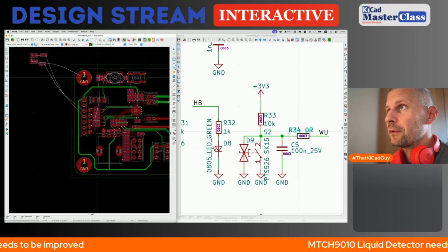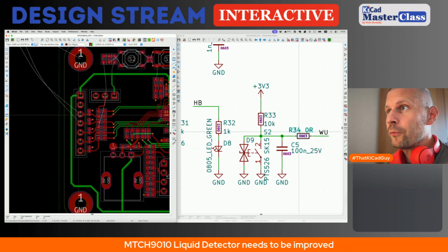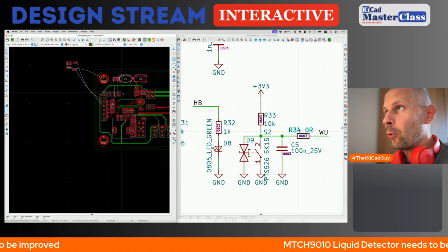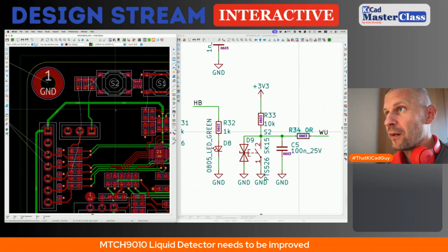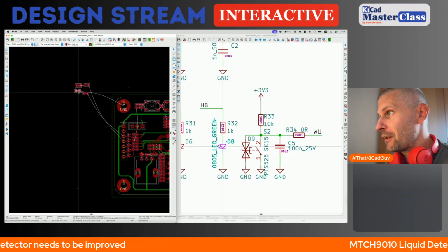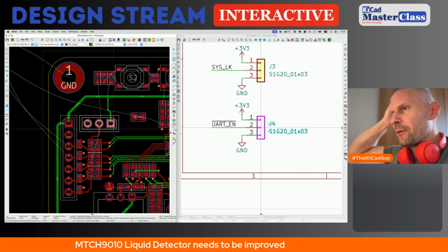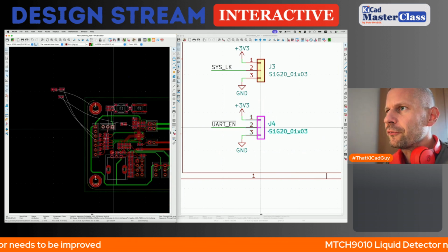I can't see any reason why we don't place it there. And now we want to monitor both heartbeat and output signals. Below the reset or below the wake up button, there is plenty of space. So I think I will place the LEDs there. What's this again? Yes, this is the UART enable jumper. I don't like the position of it.